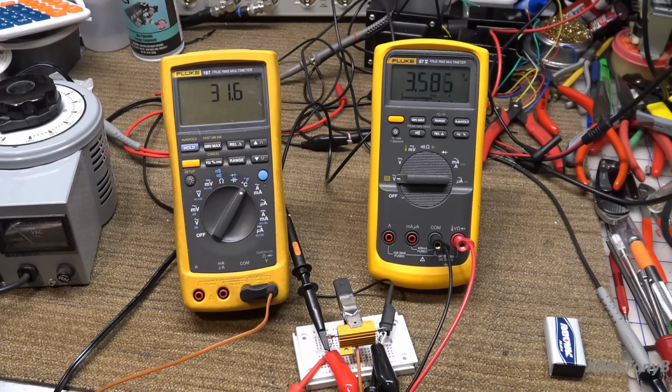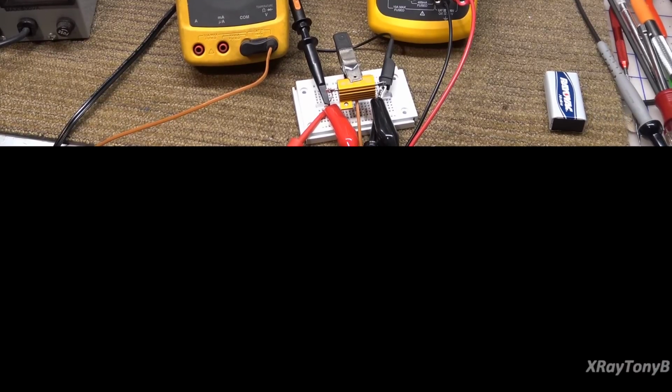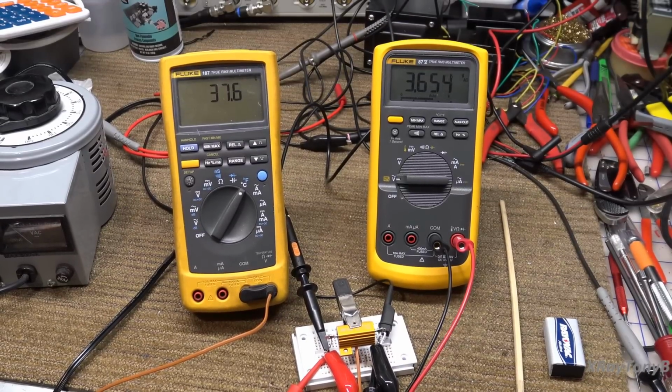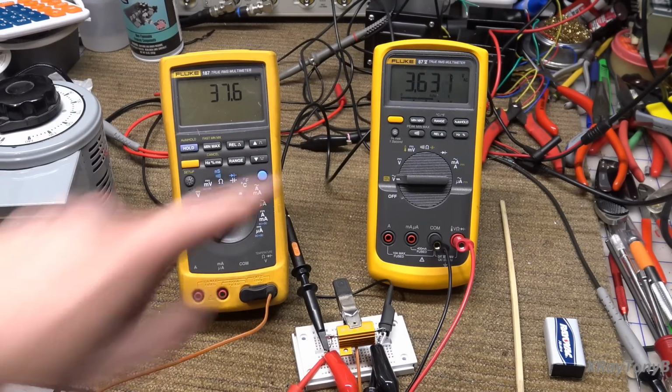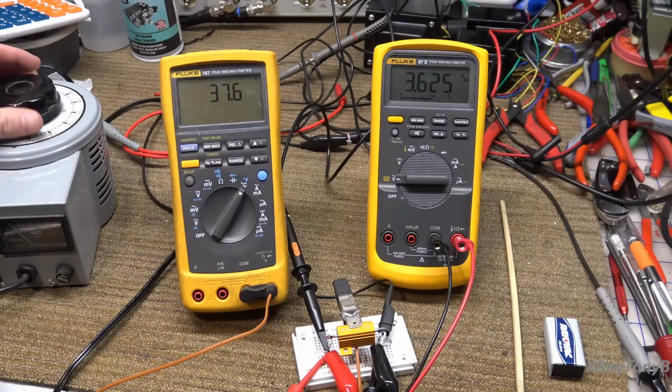We're going to give it another 5 or 10 minutes to stabilize. And we're going to see if we get that same, what was it, 53 degrees or so Celsius. Let's let it stabilize and see. So as you can see, it's stabilized. And when we do 5 volts peak, it does not match the same temperature as when we put 5 volts DC. So now let's use this silly RMS thing and see what happens. Let's set the RMS to 5 and see what happens to the temperature.